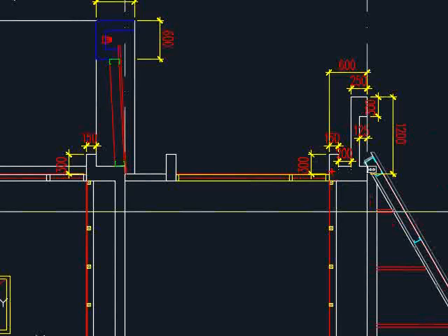You might need to have these members with shear links more closely spaced, or probably increase the grade of the shear link that you use. For example, initially you use mild steel, now you convert it into high yield steel bar as your shear link, and then ensure that there is proper anchorage within the beam so that the entire member acts as a monolithic section.